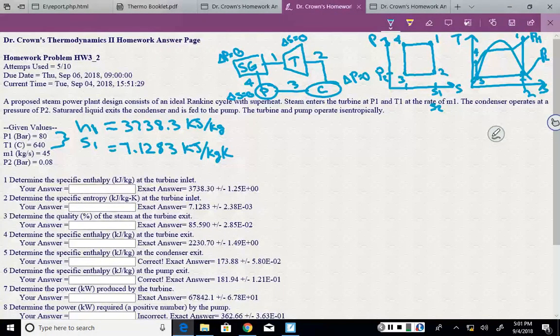Right, so now let's think a little bit ahead of where we're going. For the turbine, of course, dE CV dt. This is my system boundary. So I'm just looking at turbine 1, the only turbine. If I apply the first law to that, my control volume is everything inside the turbine. Heat transfer across that boundary minus W.